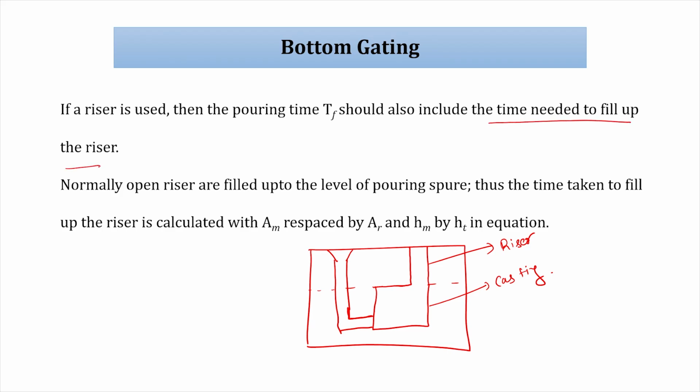To calculate filling time, you have to calculate this plus this, whether top gating or bottom gating. In both conditions, you have to calculate your filling time based on the riser as well as the casting.